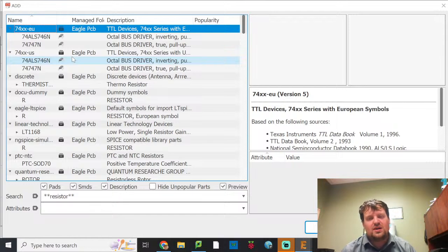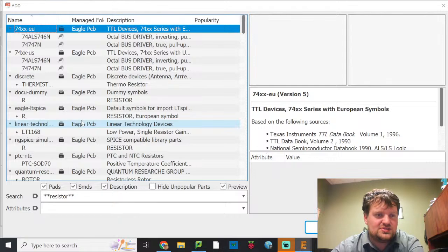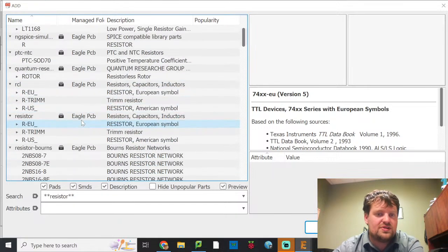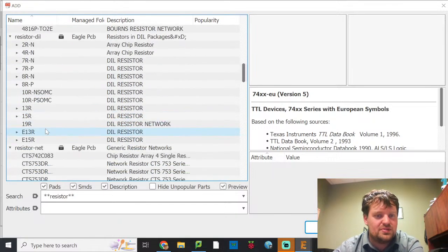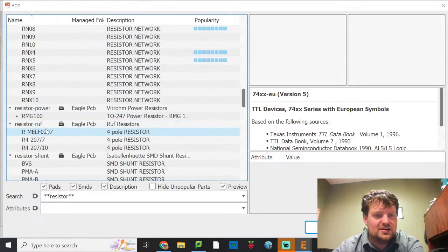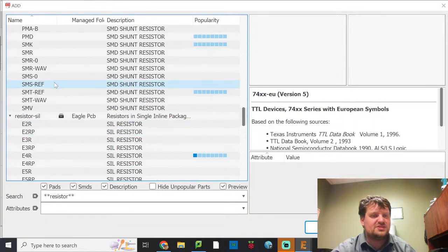And so what I'm going to do for my circuit board is pick a style of resistor that only has either 12 millimeter separation, maybe I might go as much as 16 millimeter separation. I don't need it to be all that much. So I have to keep that in mind when I go to build my board, is how are my components going to look. Now looking through here, there are a lot of different types of resistors.